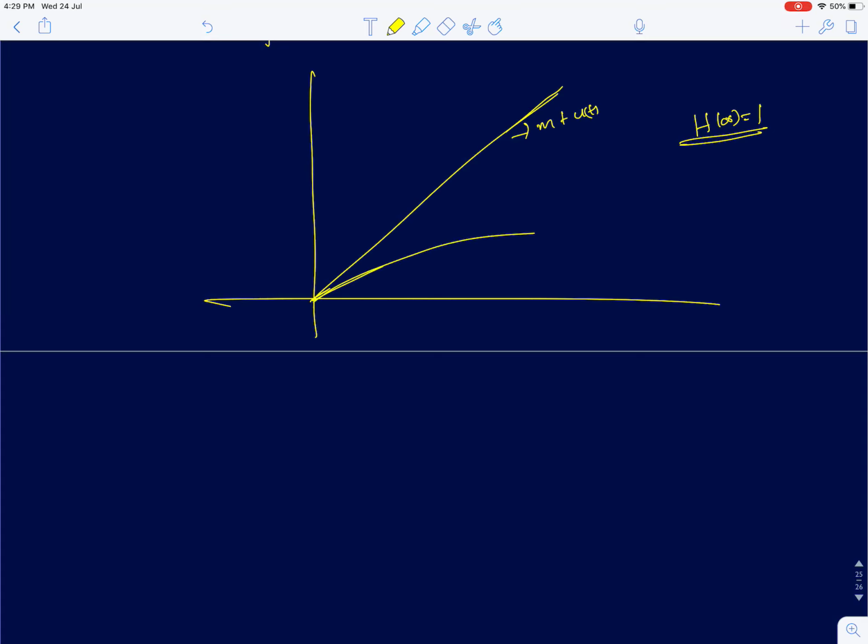The output would reach a value of m tau in the steady state. Now even though the input is reaching infinity, the output is reaching a finite value. Now if you look at the transfer function, it is s by omega p by 1 plus s by omega p. I have assumed H infinity as 1 for the time being in this system.